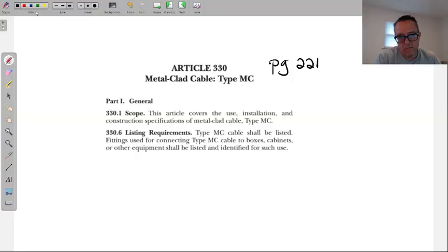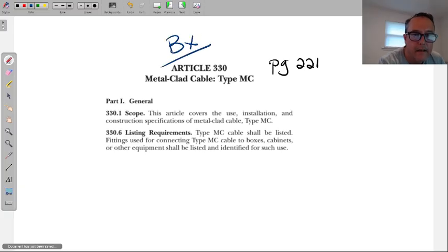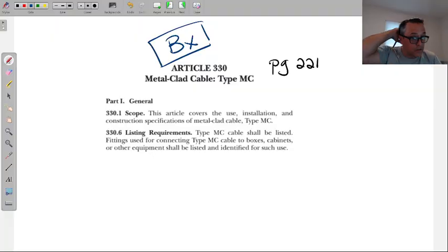It's just like Romex is NM, but we call it Romex. AC cable is actually called BX, for where they made it, which was the Bronx. And if you go into the state of New York, mostly Manhattan, but everywhere else as well, there is no MC cable. They use BX. And the difference is the outside metal is much more durable. It's a stronger metal outer coil.